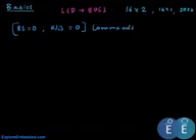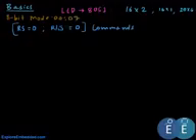Now let us start with a few basics. If register select and read write are both 0 and we send a command on the data lines, assuming we are discussing 8-bit mode, so for starters we will be discussing 8-bit mode where we have the entire data bus D0 to D7. The first command would be to clear the LCD, and this would be 0x01 in hex.